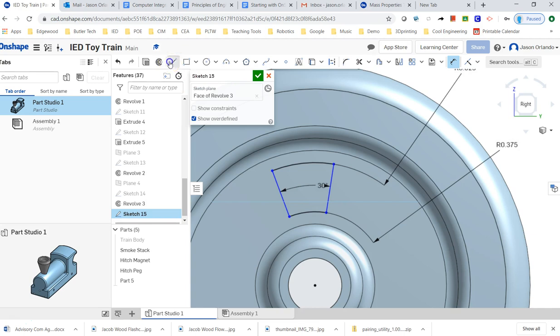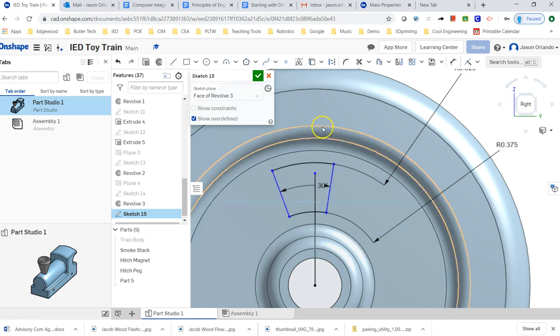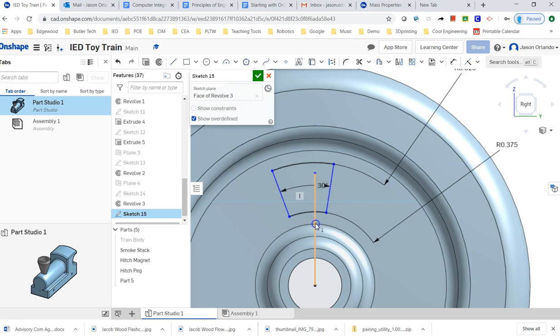Okay, and now I'm going to use another line coming up from the middle. This one is going to be vertical. This is really just a construction line for me. I'll even make it such, so I'm going to click on it, and then I can click Q on the keyboard. That makes it a construction. That's the keyboard shortcut, pressing Q for making something a construction line. I can now dimension this degree to be 15, exactly half, so that it centers it up.